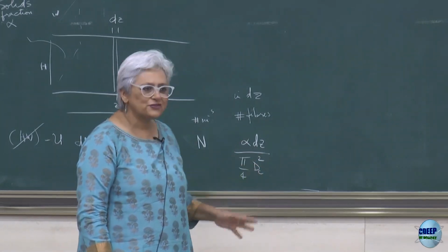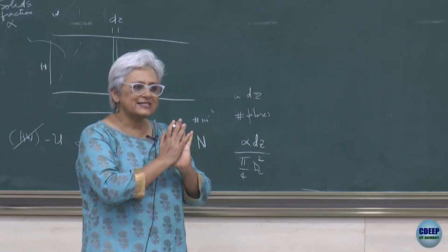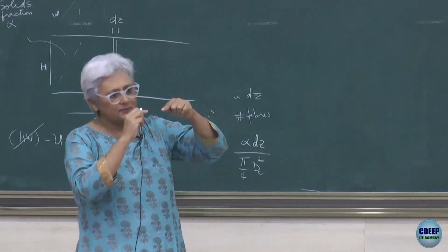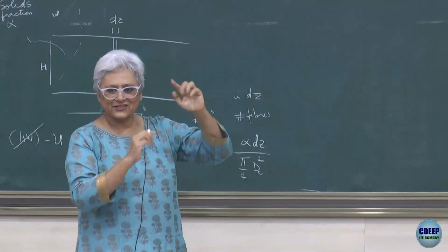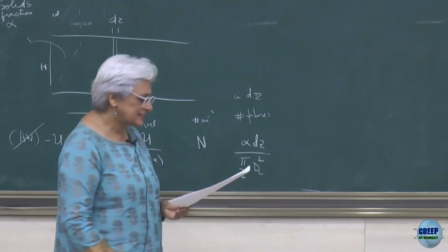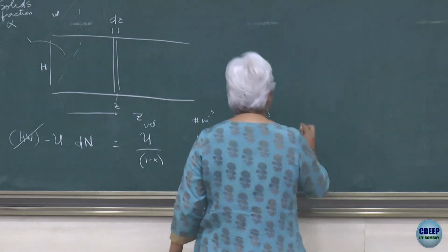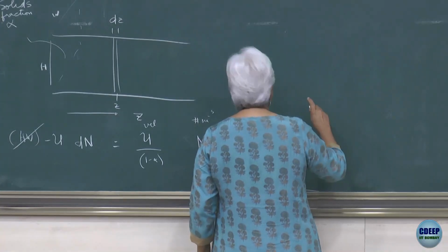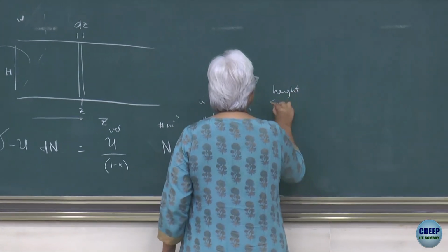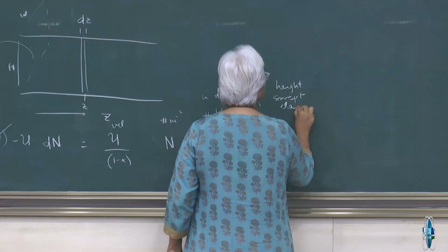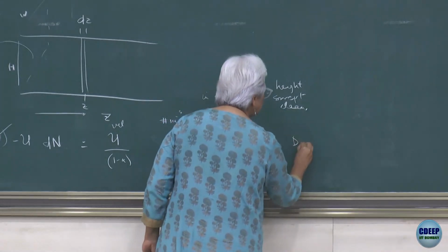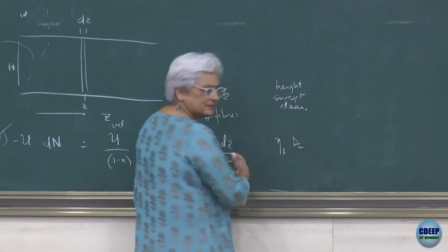And then we had talked about the fact that we can conceptualize each fiber having a single fiber efficiency and cleaning up a certain length of the fluid flowing past, cleaning it completely free of particles, right? So what is that length, maybe you want to call it height swept free, swept clean of particles, and we said that that is going to be some kind of a dc times an eta r, right?